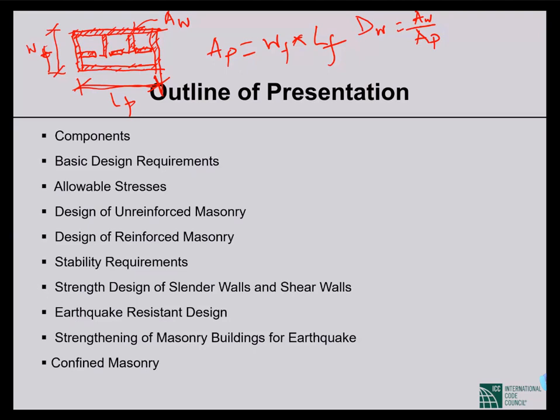That is where all the stresses are in-plane stresses. Out-of-plane bending is ignored in that type of analysis, but through some hand calculations, some out-of-plane bending is checked. But from a capacity point of view, it is assumed that all the walls act as shear walls.